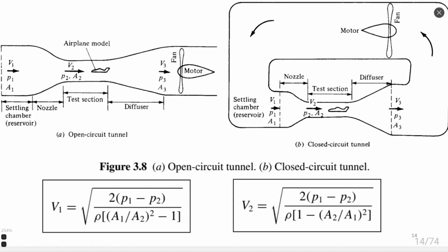Usually all big tunnels, I mean tunnels which might have several meters of cross section, the biggest one I saw is near 10 meters of cross section. In this section, 10 meters is quite a big wind tunnel. They all use a closed circuit tunnel because you need less energy for such a type of tunnel, and the energy you basically apply to such a structure is consumed by friction, by boundary layer air friction and the heating of air.